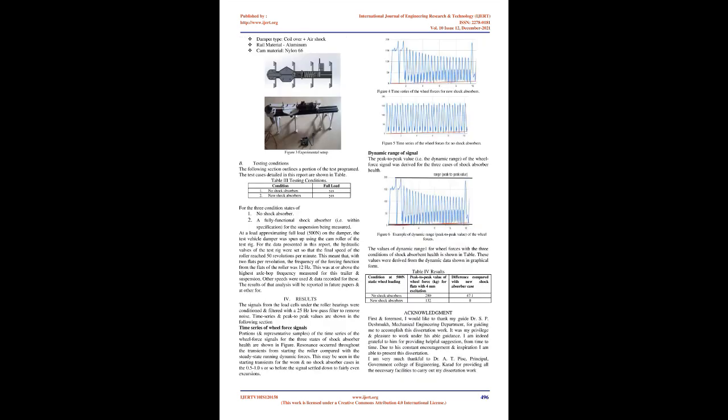A 2 degree of freedom quarter car model for analysis of a passive suspension is shown in the figure. Sprung mass, M1, represents chassis and vehicle body, whereas unsprung mass, M2, includes suspension and tire. Quarter car models have been used for numerical simulations to evaluate vibration isolation performance of the presented system. Sprung mass acceleration is the criterion used to quantify vehicle comfort performance. Lower sprung mass acceleration gives better comfort and vice versa.